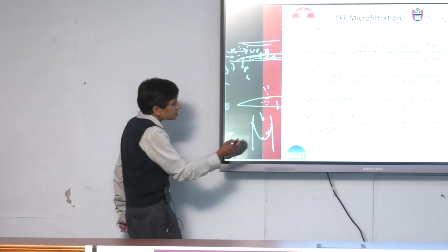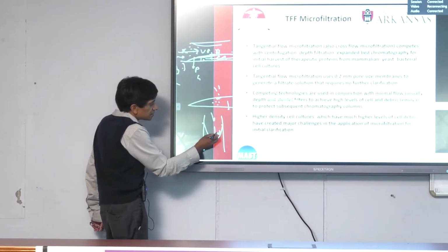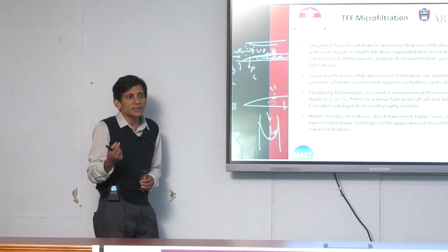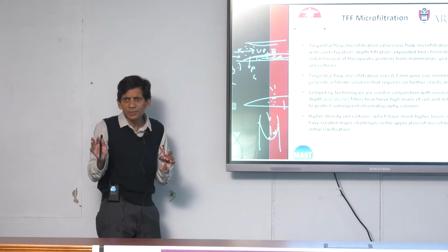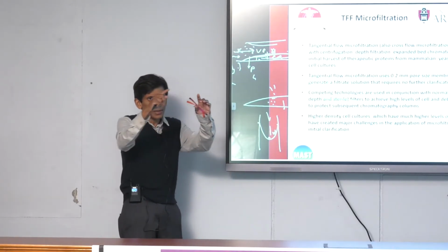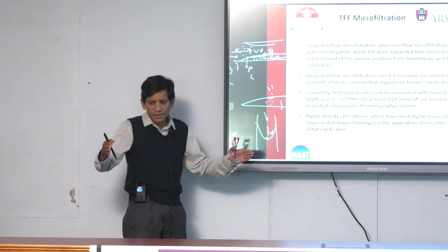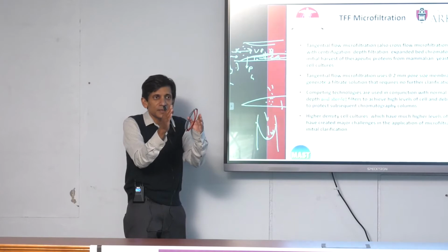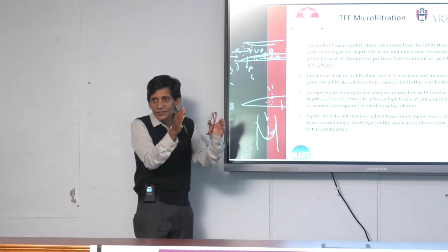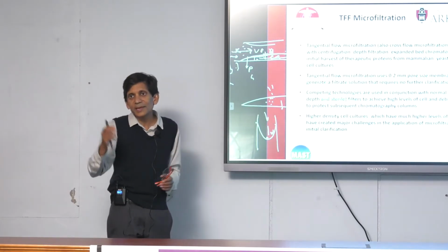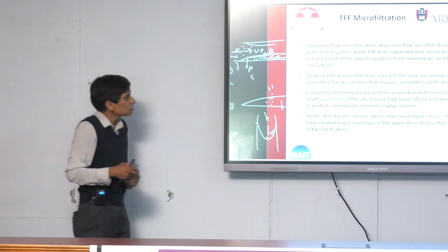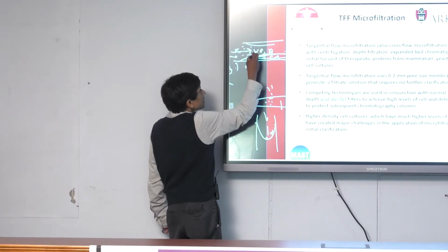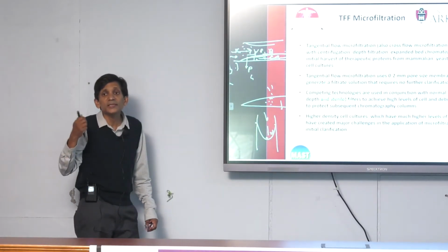And it will move to a streamline where these two forces are matching, and also what has to come into account here is the buoyancy of the particle and various other things. But just imagine that if you had a parabolic velocity profile where nothing is moving at the walls, it's moving fast in the center, and you were in the middle of that, right? You will tend to move to a position whereby somehow the shear stresses are balanced, okay? So the hypothesis here was that if you have particles moving here, the same thing happens, and there is this net back migration effect. So there's inertial lift forces.